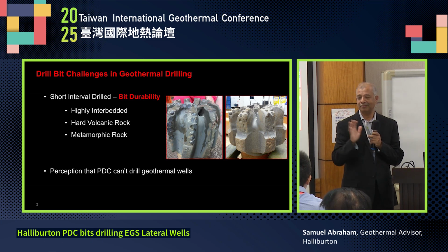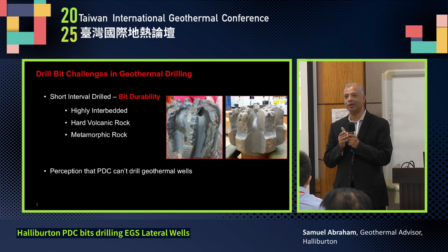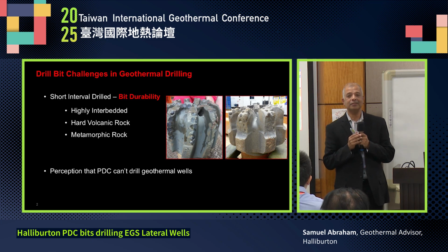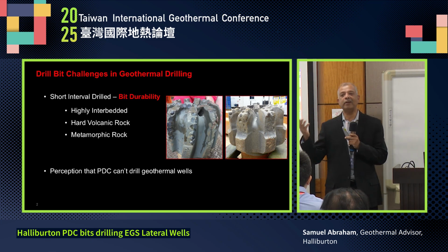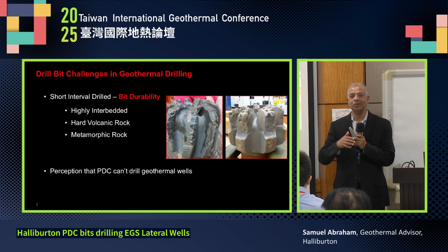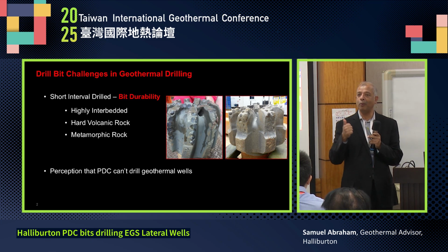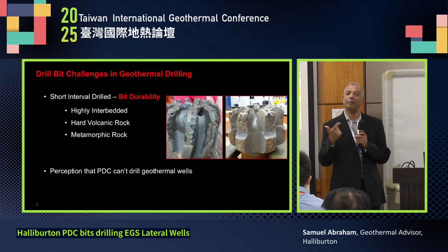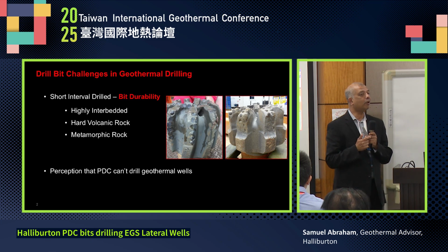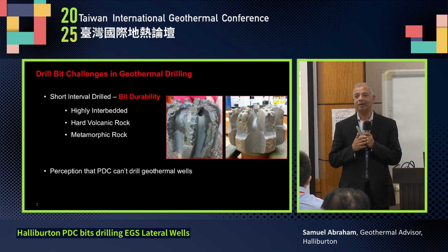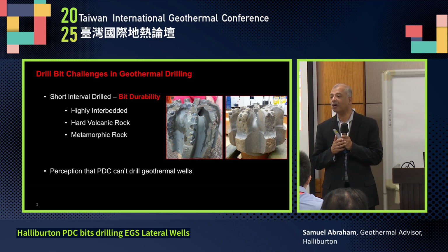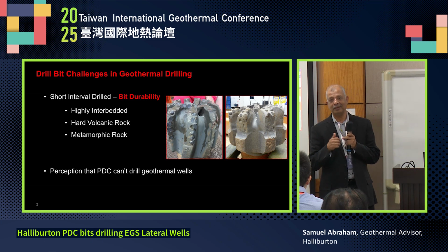you've got a rig. First of all, selecting a rig is quite important, mainly because here you're talking of drilling to depths of 3,000 to 4,000 meters, number one. Number two, some of them are vertical, but some are also going to be directional and maybe even go horizontal for a long distance.